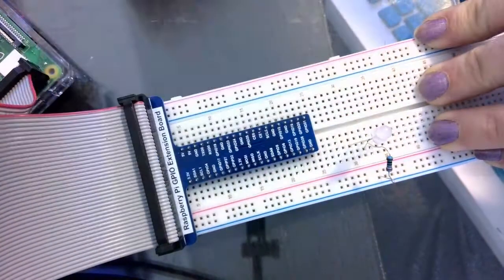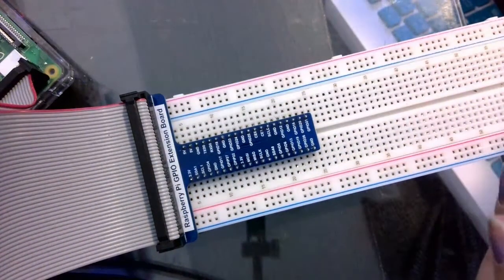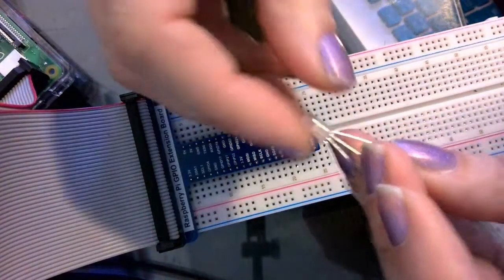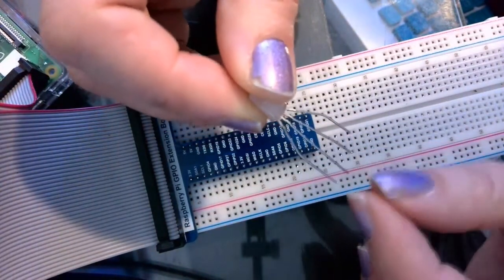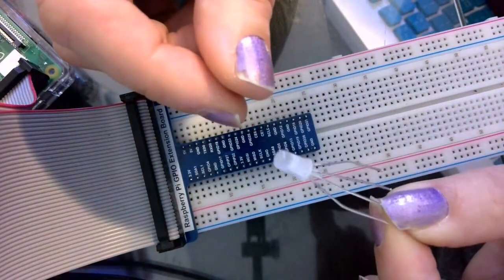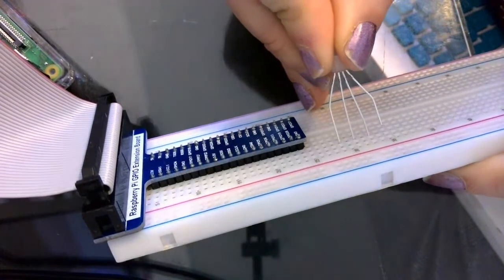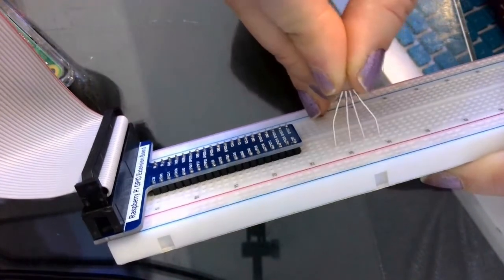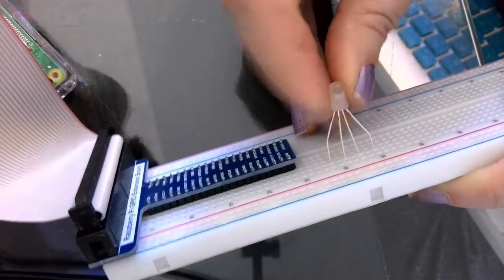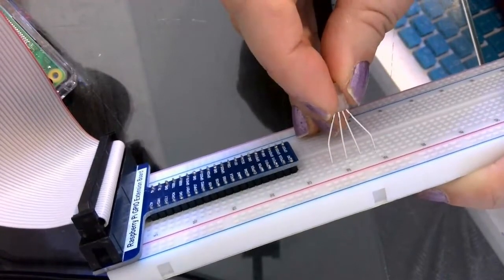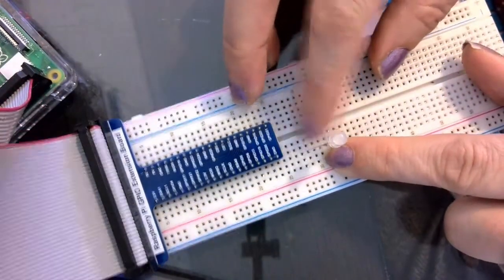Now the other option is if we have a common cathode. So that would be my other one. And it looks exactly the same as the common anode. Again, we're going to test it by finding the longest leg, and keep an eye on that while you fan the others apart enough that you can plug them into your breadboard in 4 different rows. And if this is a common cathode, then the red, the green, and the blue legs all share a ground in that common longest leg.